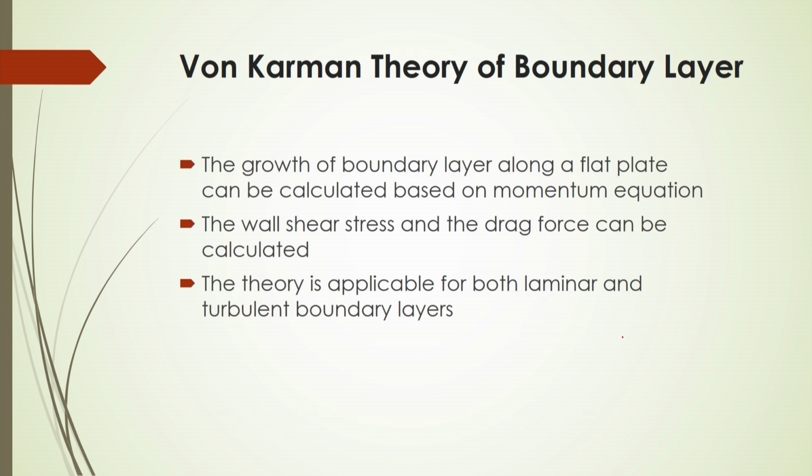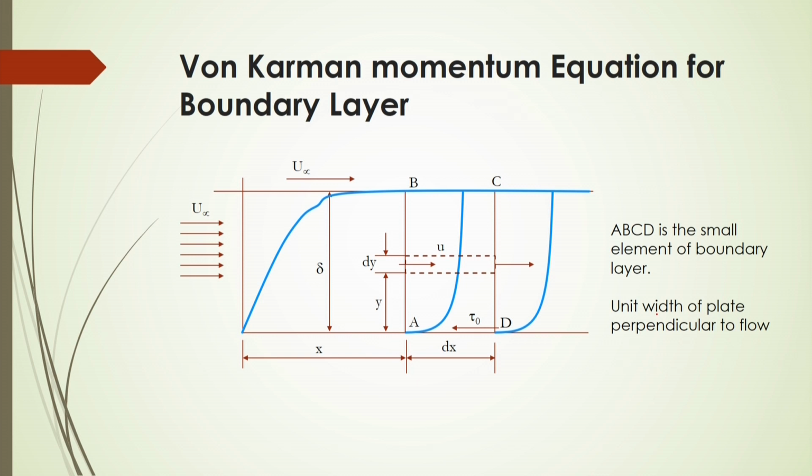If we place any flat plate, we can calculate how the boundary layer grows based on the von Karman theory, and the theory is applicable for both laminar and turbulent boundary layers. In this case, the wall shear stress and the drag force can also be calculated. So, let us see the von Karman momentum equation for the boundary layer.